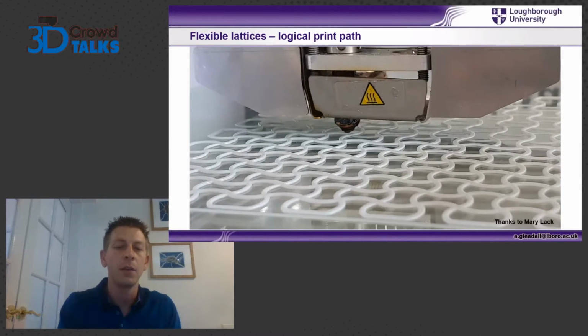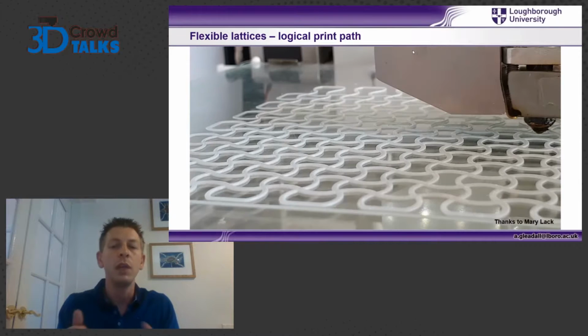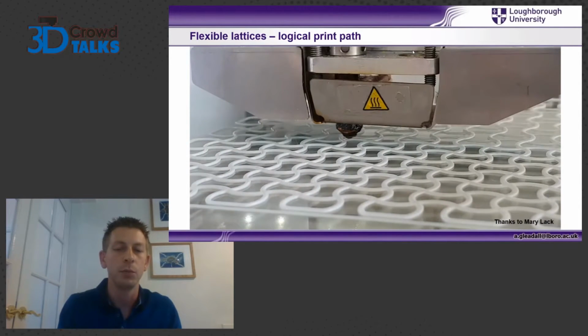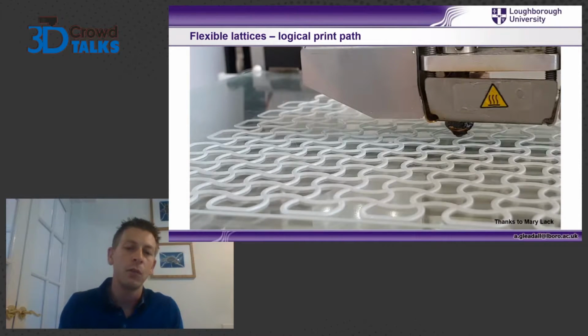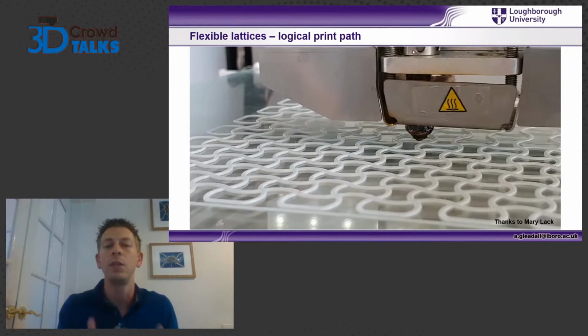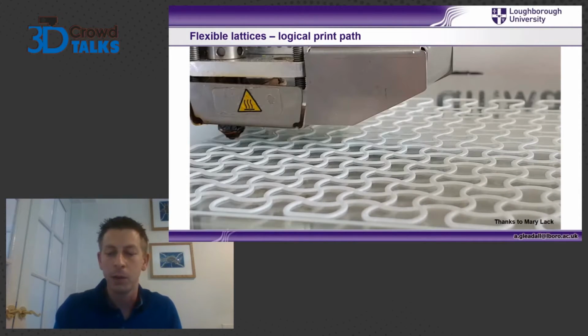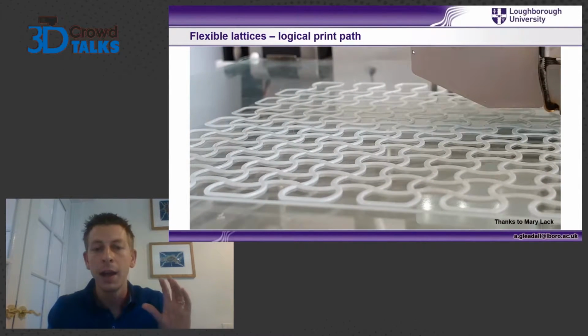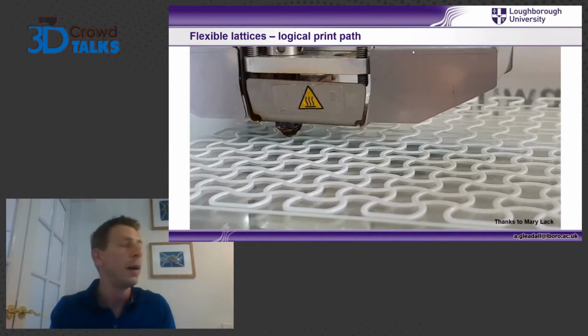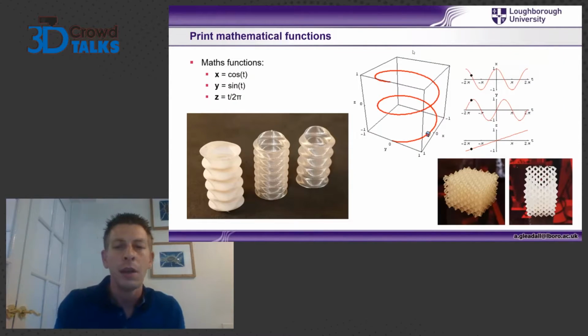So when you take this off the print bed, it ends up being really weak, and as you stretch it, it's made of a flexible polymer, it begins to break in all these points. Whereas when we print it like this, it's really smooth and continuous, no defects, and much, much better quality. So again, very simple use of custom G-code, but achieving a really nice quality part in the end.